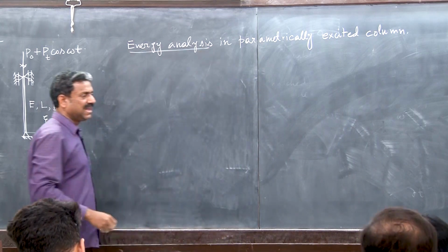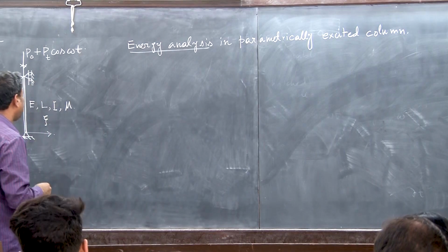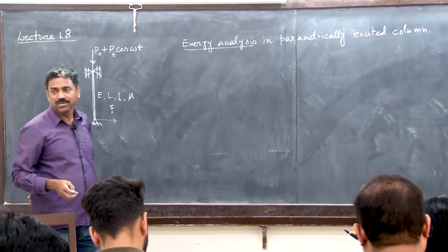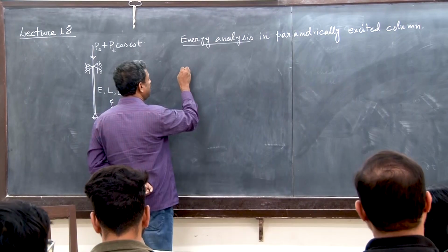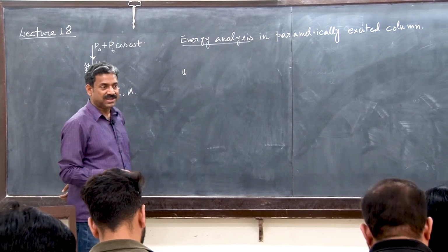So you see that here, what is the input energy to the system? This load P0 plus Pt is working through the axial deformation u, because of the out of plane displacement.